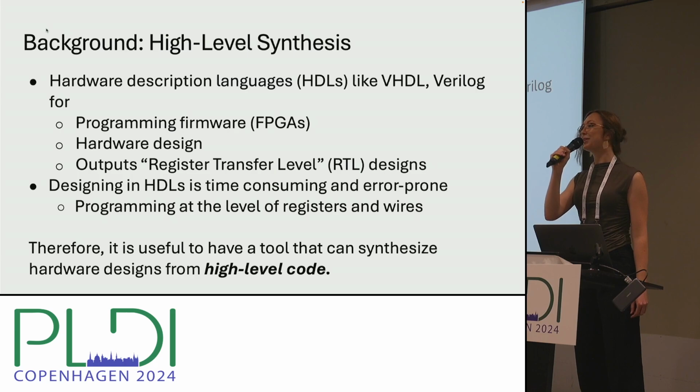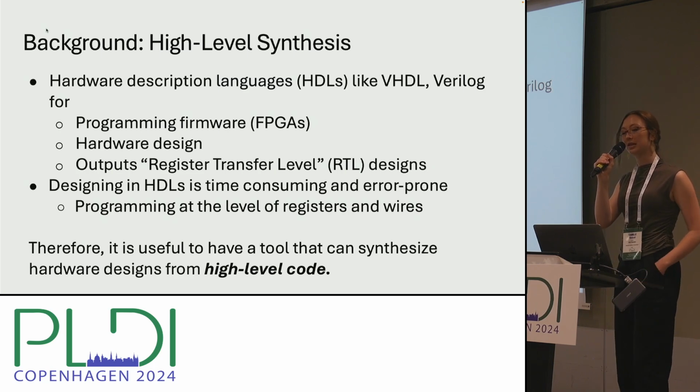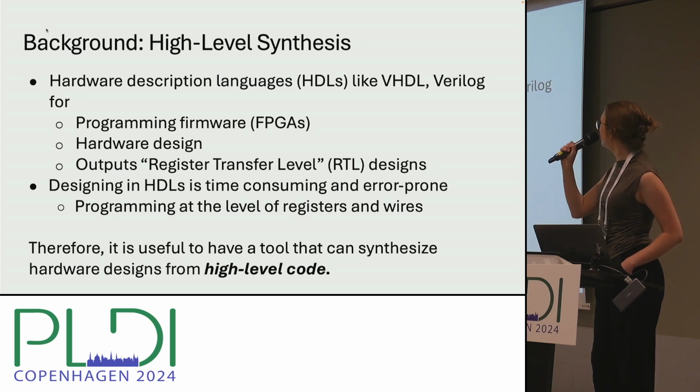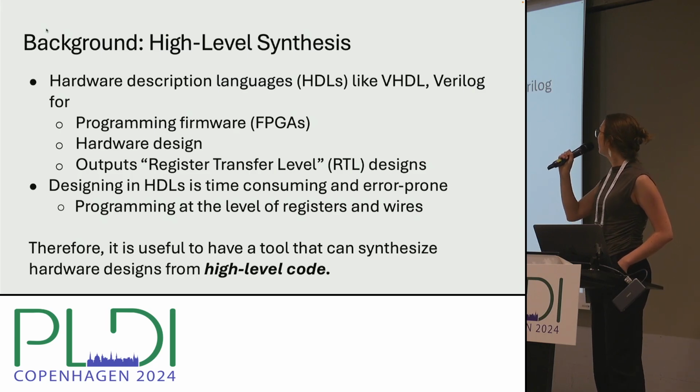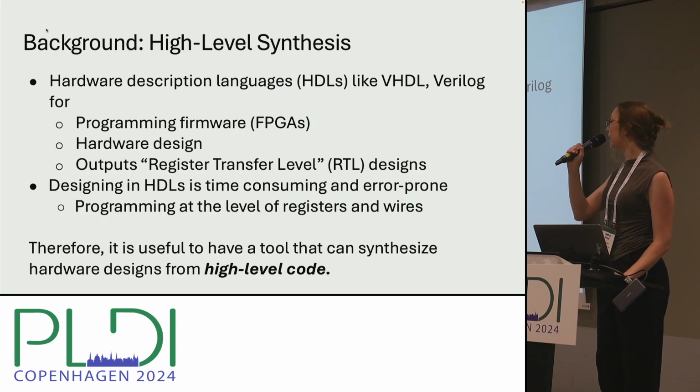Okay, so now also a bit of a repeat, but we have some background on high-level synthesis. We have hardware description languages like VHDL and Verilog, which are used for programming firmware as well as hardware design for ASICs. And this outputs RTL designs, but this is time-consuming and error-prone, and it requires someone to be somewhat of an expert in writing in these hardware description languages. So wouldn't it be nice if we had a tool to go from a higher-level language like C, in this context I guess C is a high-level language, and take it to the RTL design.